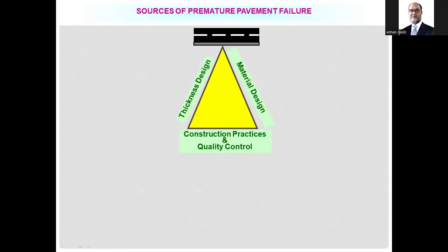We'll actually take this in a separate chapter as traffic impact and how to calculate. This is just an introduction. That's why we are stopping at that point, the magnitude and the amount the road could be damaged by allowing more vehicles that have more than 8.2 ton of single axle load.